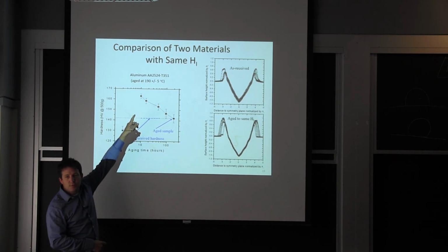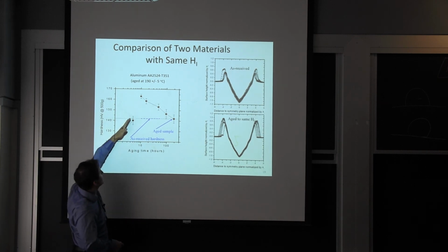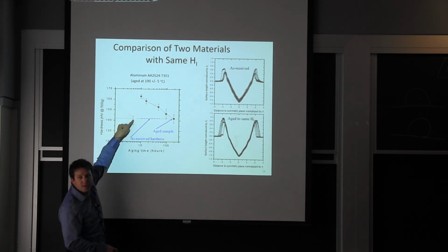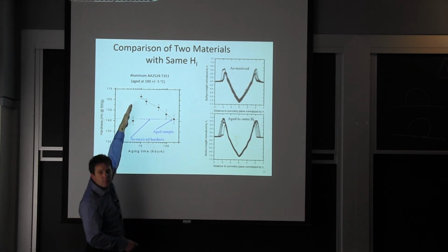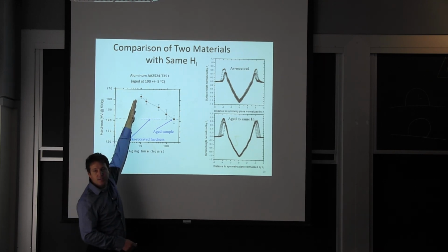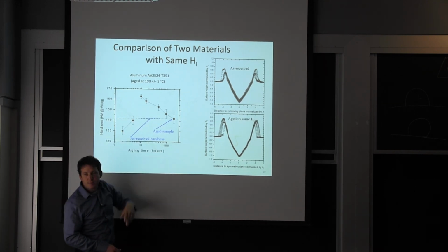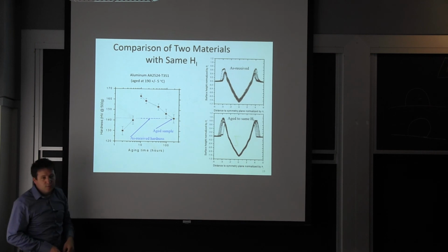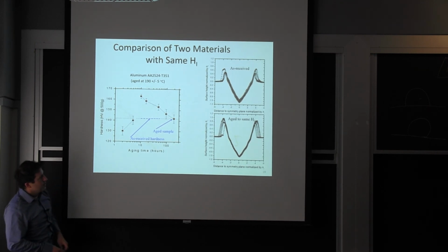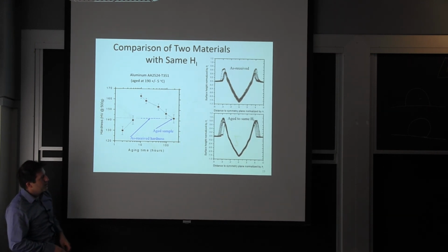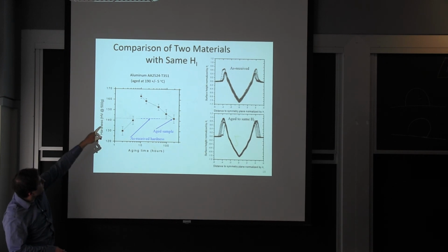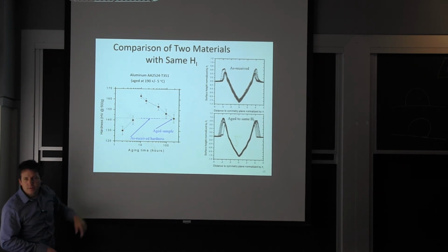It started as a T3, so we don't see as much of the beginning. I got 2 points here, but it should show more of the increase here and then the decrease. If it came straight off the quench, it'd be different, but it's exactly that 2024 type material that actually ages at ambient temperature.